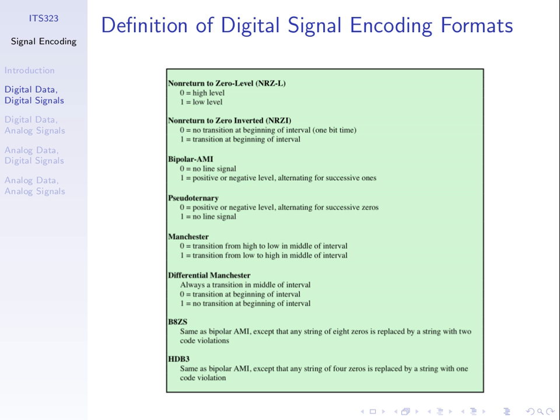But you can think of Manchester encoding as, if you want to send a bit 0, if this is the duration of the pulse, you send from high to low. You send a signal which has a transition in the middle of the signal element from high to low. Maybe to make that clearer, this is the signal. And with a bit 1, from low to high.